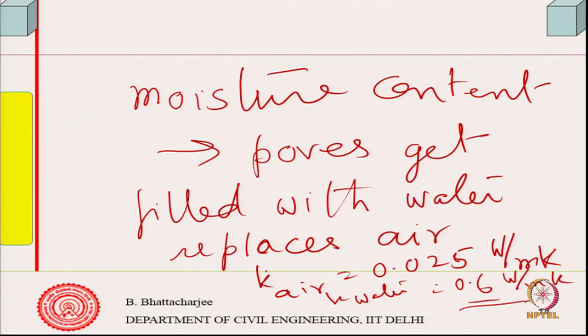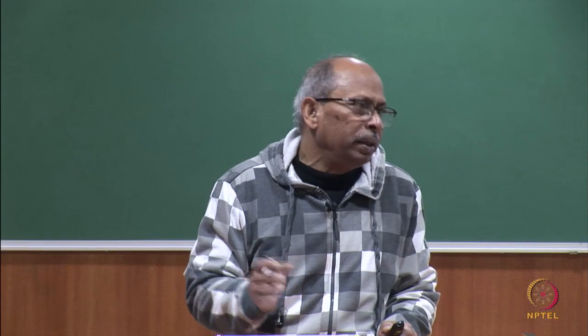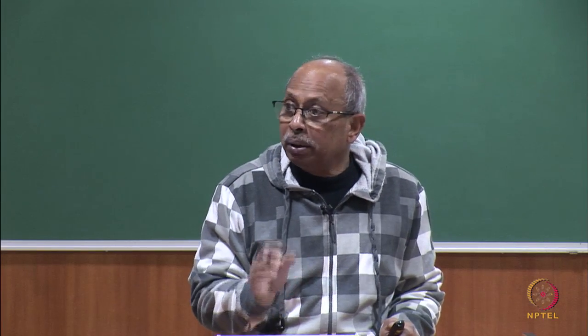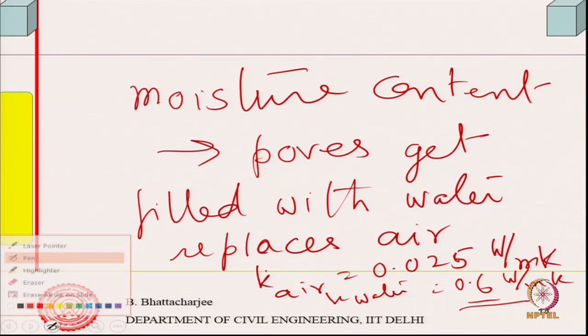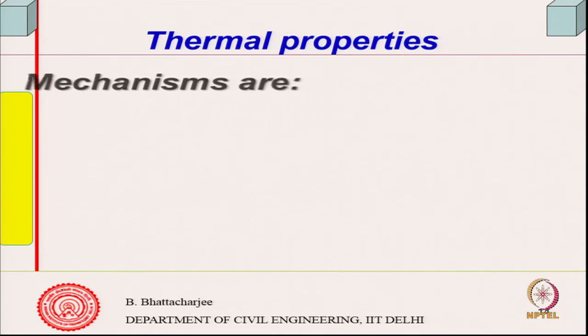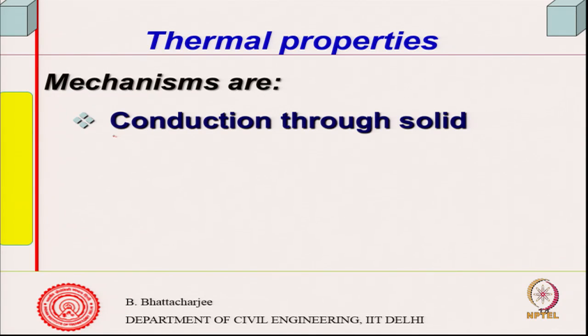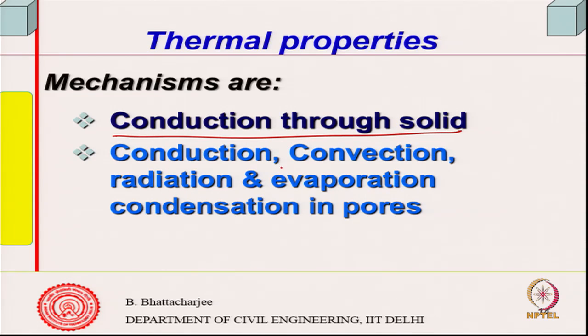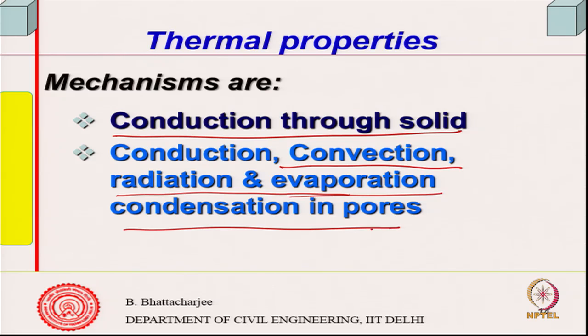Therefore, when the pores are moist, saturated, it will conduct, and also when partially moist it will conduct. So, let us see the mechanisms. Mechanisms are conduction through the solid, conduction, there is possible convection and radiation, and evaporation condensation in pores.